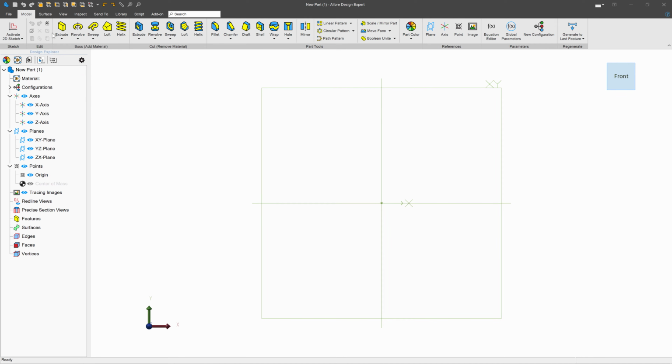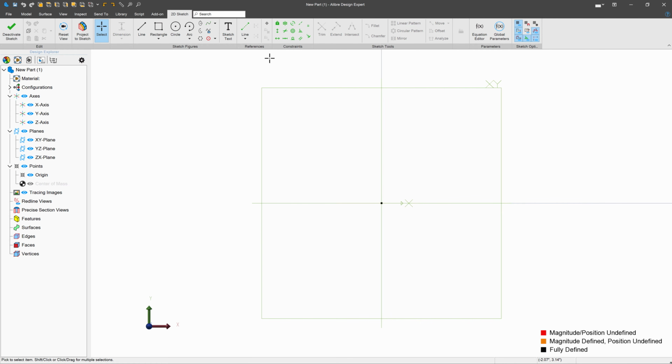Well, modeling in CAD can have its ups and downs, and that's what we're talking about today when we're going to make an office chair riser that goes up and down. So to start our riser, I'll make a sketch on the XY plane. I'll make an angled section and then a vertical section, and then come back around.